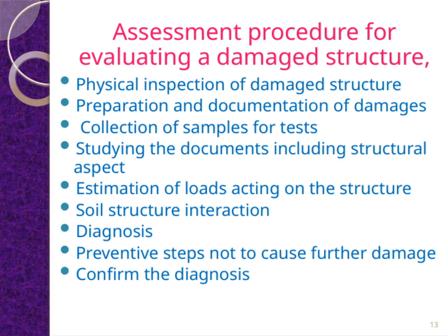Collecting samples for tests is another key component. These samples, whether of concrete, steel, or soil, provide vital information about the material properties and any deterioration that may have occurred. Alongside this, studying relevant documents, including structural plans and previous inspection reports, helps us understand the original design and any modifications. Estimating the loads acting on the structure is also fundamental. Knowing the forces and stresses involved allows us to identify potential weaknesses. We also need to consider soil-structure interaction, which looks at how the foundation and surrounding soil influence the structure's behavior.